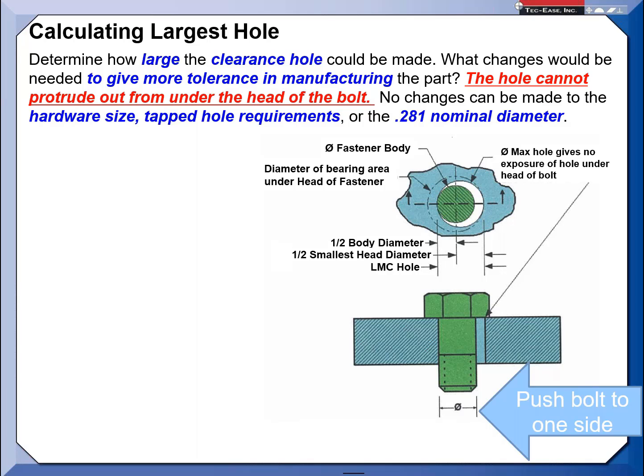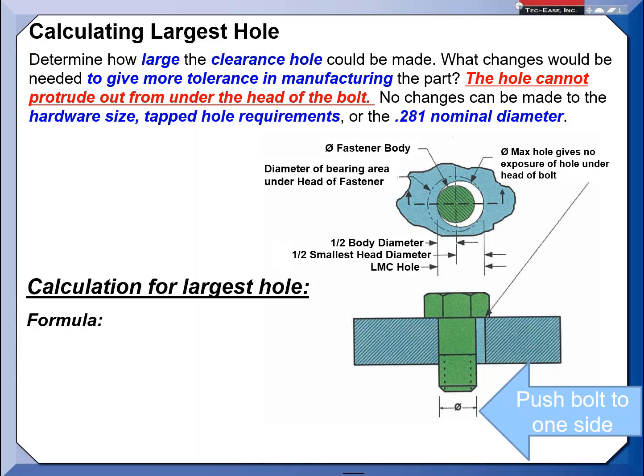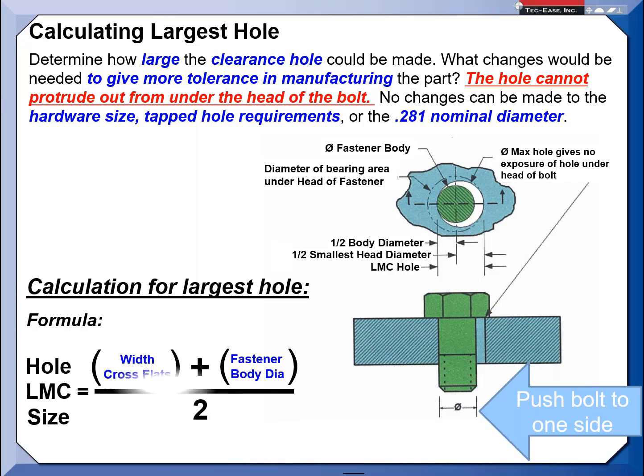If you actually take a look at the ASME standard on drill sizes, you're going to see the drill sizes are held pretty tight for the actual tool. Now, when the tool is placed in a machining center or process, there's some variation that kicks in with the tool head and the repeatability of the machining bed. But here we're showing you there is a method, not a standard, that you can calculate.